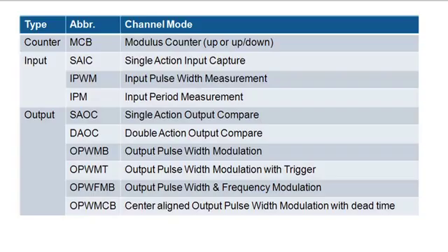And after the second edge is detected, then a flag goes off, which can be an interrupt or a DMA. And then software must read the 2 times and subtract the difference to get the pulse width or the period. Okay? We just record the times. It's done by hardware, you set it up.